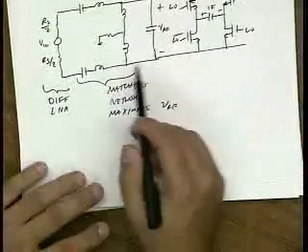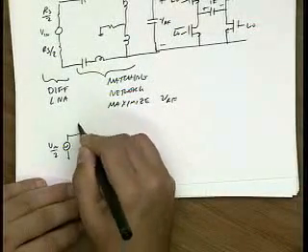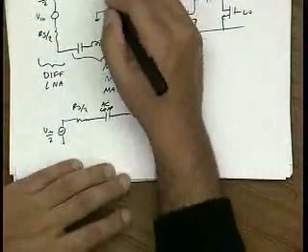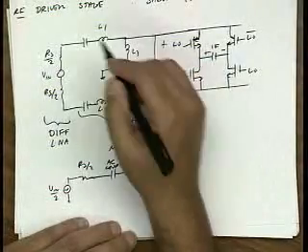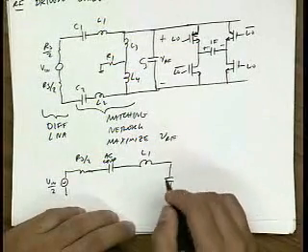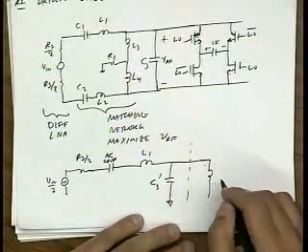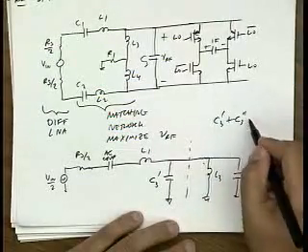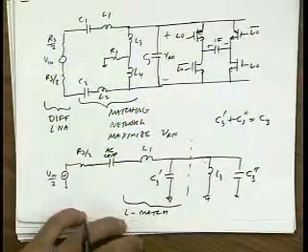Okay? And so I can decompose this into an equivalent half circuit. I have Vin over 2, RS over 2. I have some AC coupling, so this is nothing. Then let's call this L1, this L2, this L3, this L4, this R1, okay? And let's call this C3. So I have first a matching network, L1, C3 prime, and then I have a tank, L3, C3 double prime, where C3 prime plus C3 double prime is actually equal to C3. So you can see here that this is really an L matching network, and this is a tank.